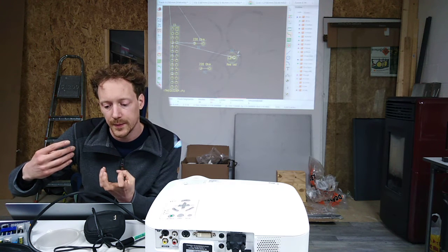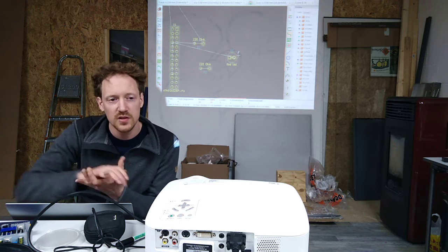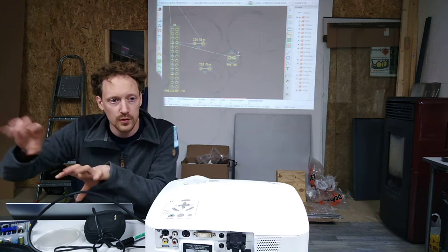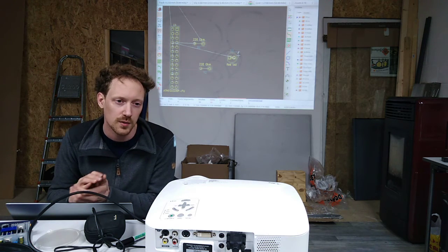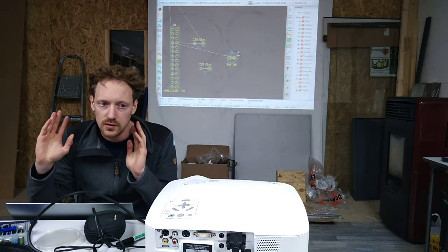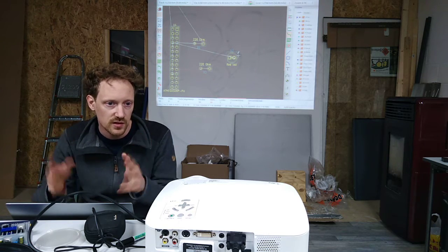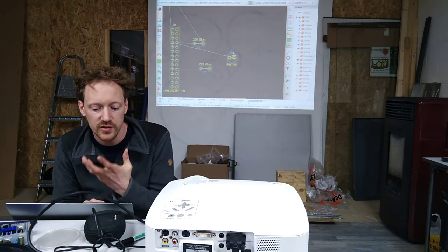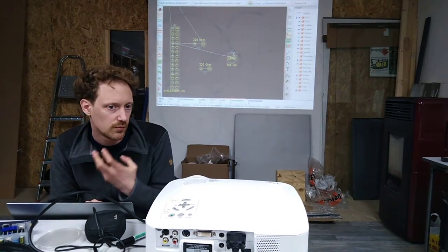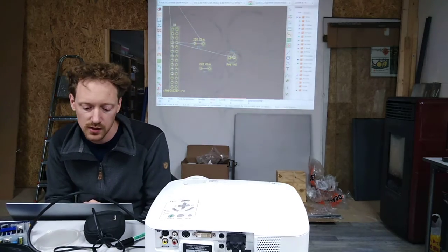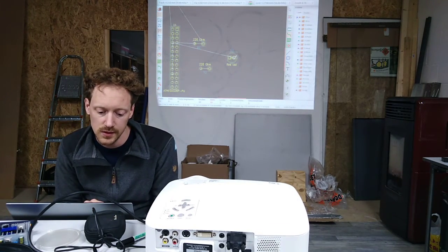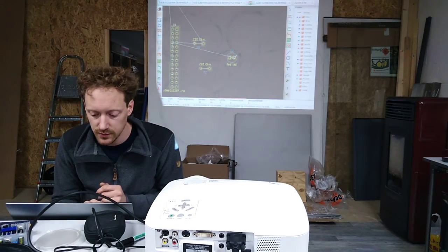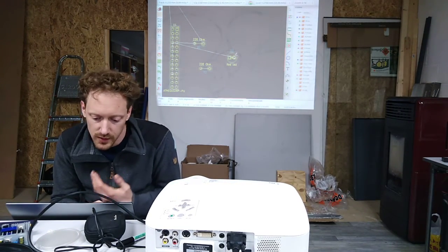In chip design, you have a phase that's called place and route, and it's exactly that: place all the components and route them together, and that's an NP-hard problem. So basically you use a SAT solver to try to solve this problem, and for small components it's probably doable, but for large problems, it's manual.